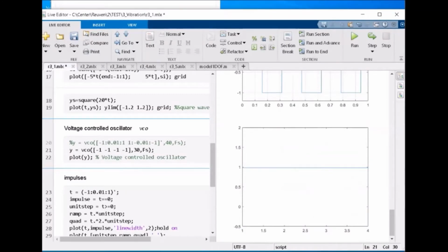What we did, we just used this voltage generator with the first parameter being the number -1. It's not a negative frequency. We just ask the generator to produce zero frequency, just a DC signal without any change in its frequency.